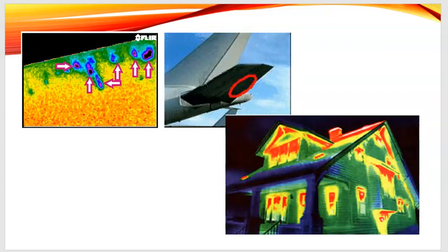There's just some different infrared images. In this case, they've got a jet fighter, or that's not a jet fighter, an airplane. You can actually use infrared to see if there are leaks or the shell is starting to get loose, and it will let some moisture into it. As the moisture gets in, it gets a little cooler or transmits the heat a little bit better. You can use an infrared camera to see which rivets or fasteners are starting to get loose, is there a leak.